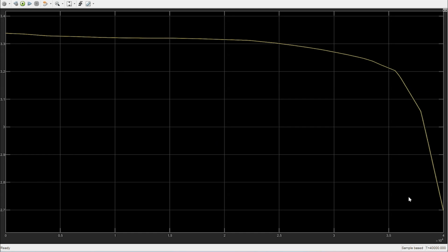In that way, you can get a very accurate model of a lithium ion cell where you can mimic the voltage patterns with much more accuracy than the equivalent circuit models. In equivalent circuit models, it is not so accurate because we are not including electrochemical processes like this. So this is the kind of result that you can expect once you simulate a single particle model.